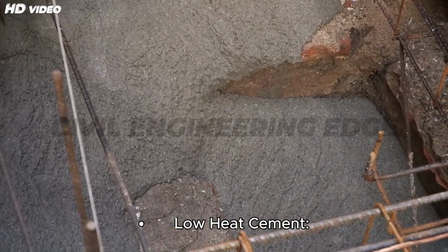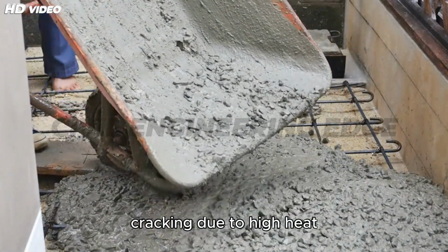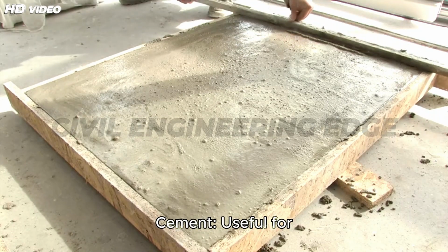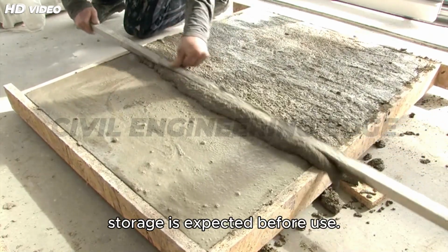Low heat cement. Essential for massive concrete pours like gravity dams, where thermal cracking due to high heat of hydration must be avoided. Hydrophobic cement. Useful for regions with high humidity or rainfall, especially where long storage is expected before use.